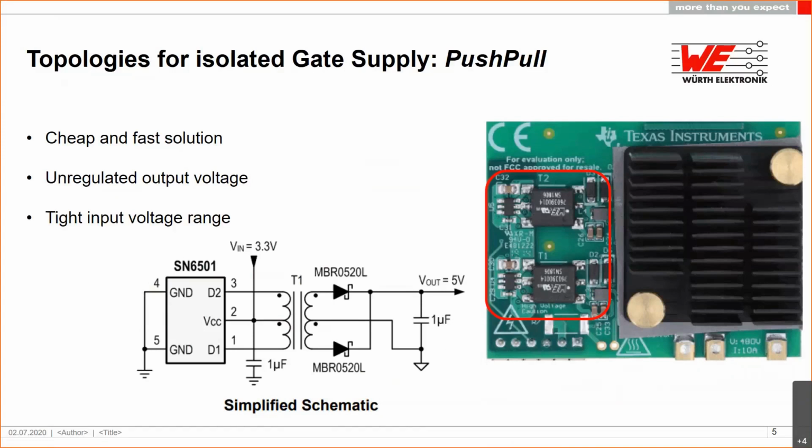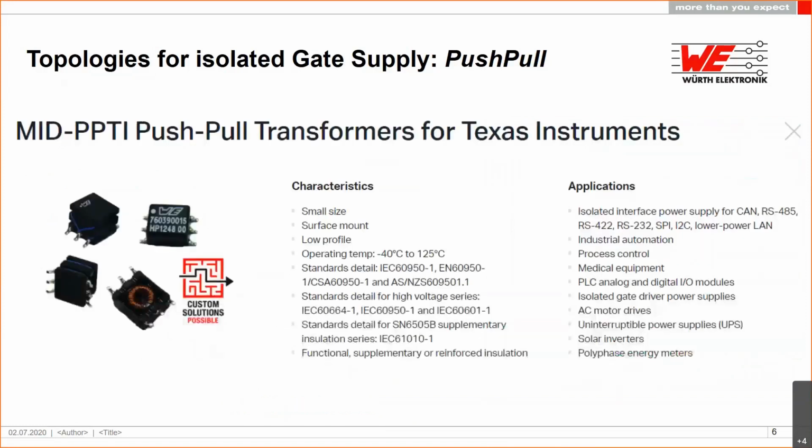And from the size perspective, in power density, there are better solutions, as we see in the next slides. If you would like to do a push-pull design, because there are advantages, especially on the price side, there are many different transformers already available with different isolation requirements, from reinforced insulation to the basic insulation. Everything is there with different turn ratios to meet different input or output voltage requirements. So there's no need to make a special part for yourself. There are always off-the-shelf products for this.